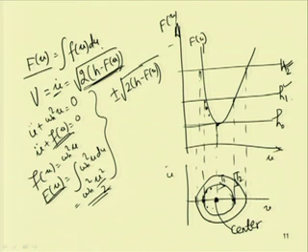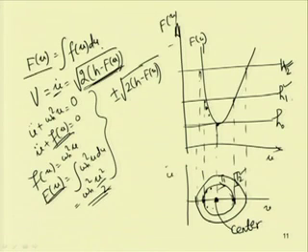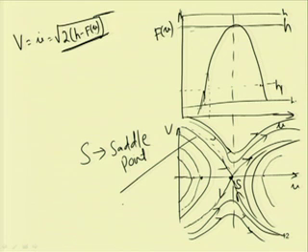Similarly, up to this I can find two points, and if I join these points, I can get this trajectory T 2. And in the case of a system where we have a maximum potential energy, in the previous case we had a system with minimum potential energy, that means potential energy decreases, and in this case we have a maximum potential energy. Maximum potential energy corresponds to an unstable system. So, in this case, corresponding to this maximum potential energy we have a saddle point, and corresponding to minimum potential energy we have a center in the system.